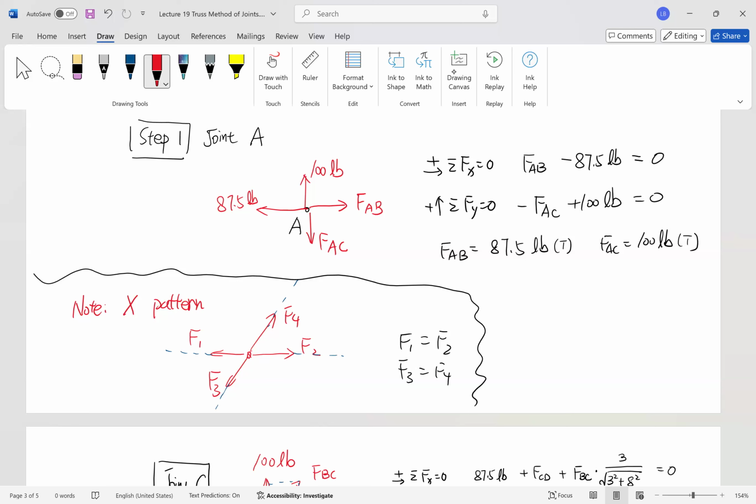So now you see that both the T pattern and V pattern are just special cases of the X pattern here. And the X pattern is just a special case of equilibrium. But behind those, it is actually the geometric sense of equilibrium of a truss structure. So get familiar with that. It is pretty important to build a sense of structural engineering.